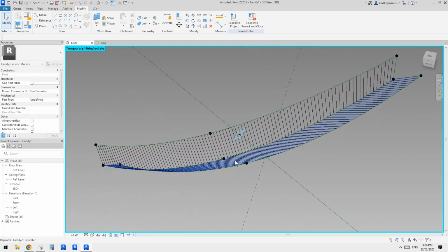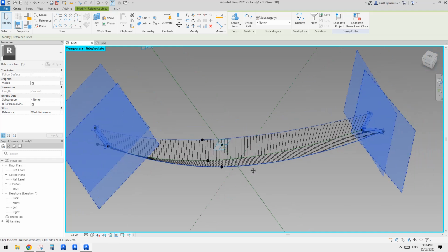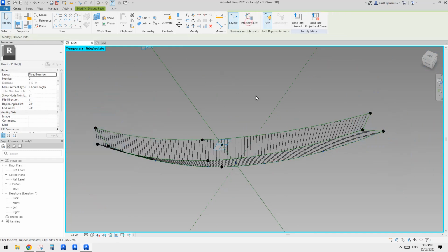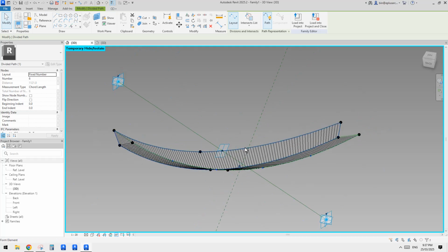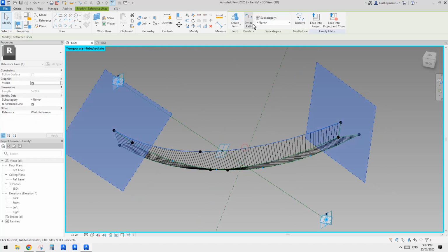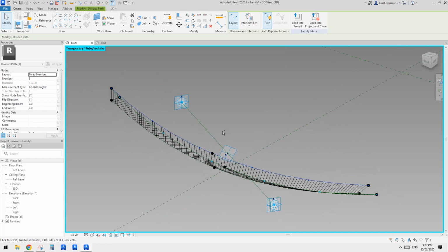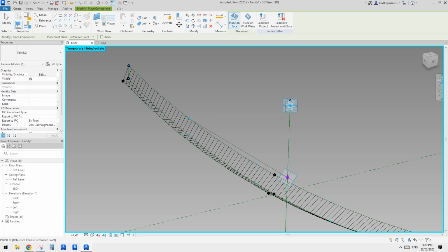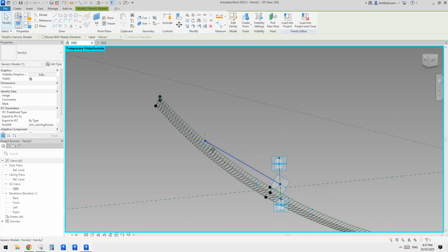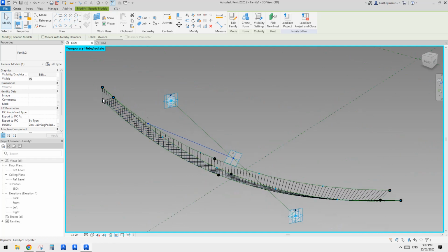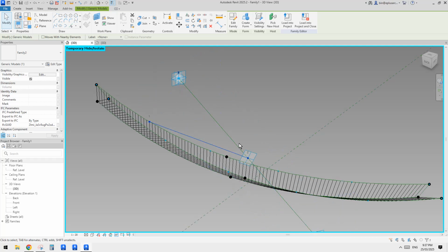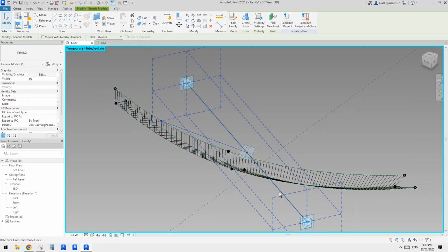So for those structures, for example, we can create another one. Like I'll Tab select this one, create a divided path. This time I'm probably just using 6 as the number. So another one here, and the divided path also uses 6. And then we already have this adaptive family, right? So we can connect here to here, for example. So we have a structure member to connect this thing to this point, to this horizontal member, right?